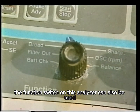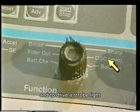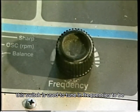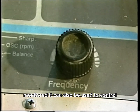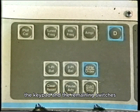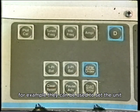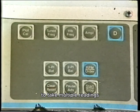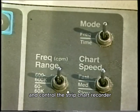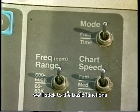The function switch on this analyzer can also be used to test the condition of the batteries and to drive a strobe light at specific frequencies. This switch is used to tune in frequencies to be monitored. It can also be used to control the speed at which the strobe light fires. The keypad and the remaining switches allow the operator to control a number of other functions. For example, they can be used to set the unit to take multiple readings, convert the readings from English to metric units, and control the strip chart recorder. However, for our purposes, we'll stick to the basic functions.